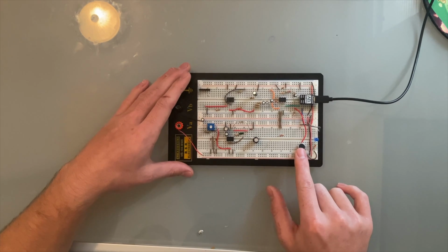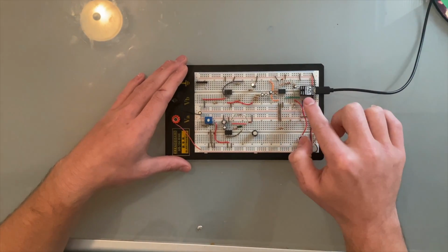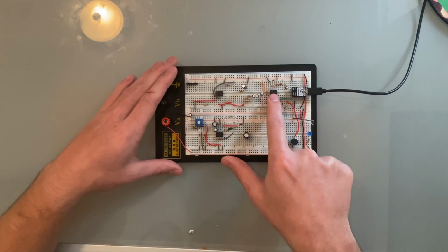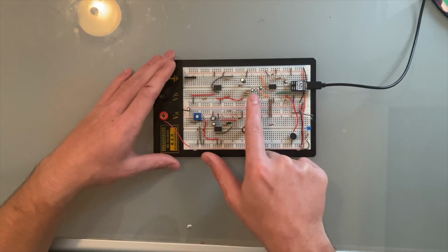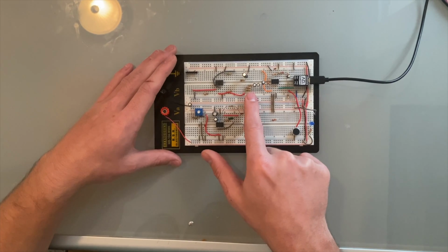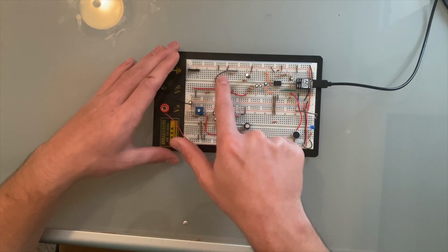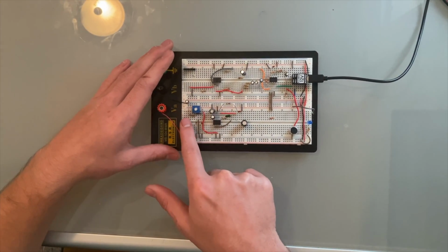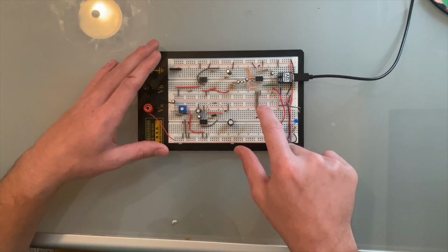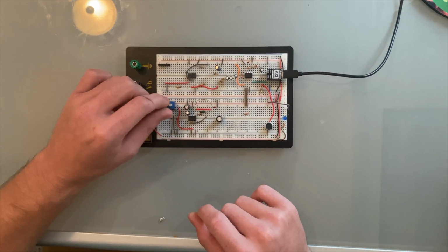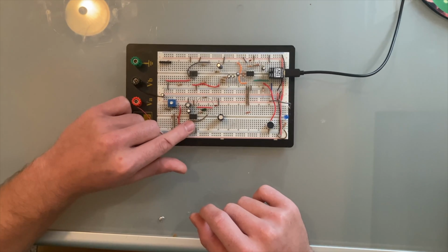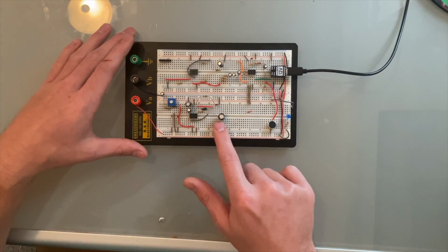Here's the microphone. Feeds through the biasing network into those 2 stages of gain we saw. There's 2 op amps on this one chip. Then it goes into this summing amplifier right here. Comes along, goes into the summing amplifier gain stage, which then feeds into the actual audio amplifier right here. This controls the volume of the circuit. And this is the diode clamping right here. And this is the audio amplifier. And it comes out right here.